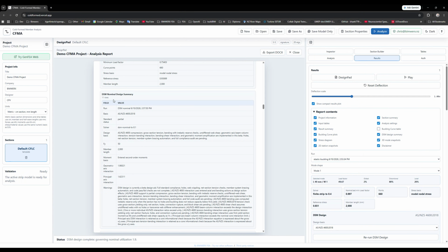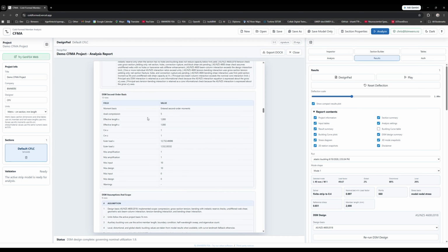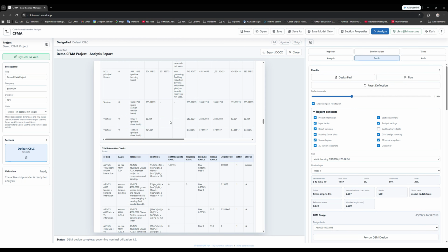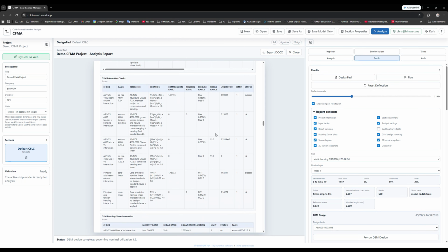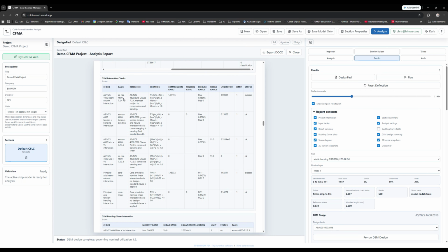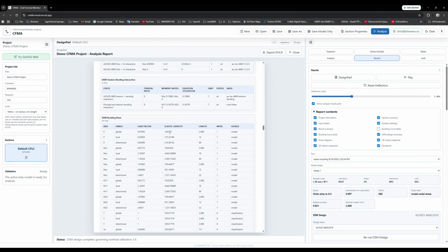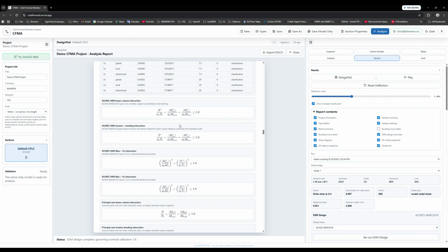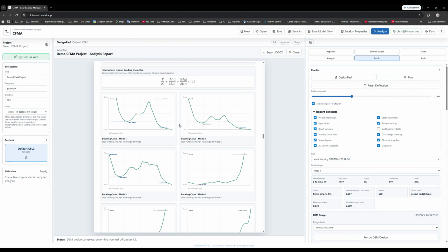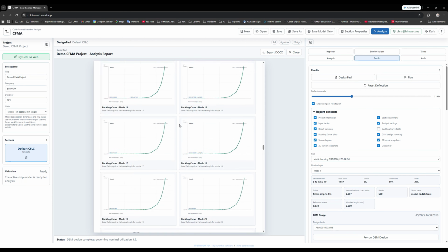And you can see now we get to the DSM nominal design summary. We've got our second order basis summary, assumptions and scope, the audit trail, the nominal checks against the standards and where they are relevant. We've got the interaction checks, we've got bending shear interaction, we've got tension bending interaction, buckling analysis results, and then formula used for the outputs. And then that's followed by the buckling curves for the different modes for the project.